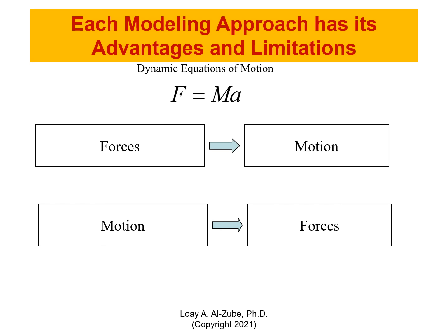The second step is formulating the equations of motion. And we have 2 ways. That's called the dynamic modeling approach. So we have something called forward dynamics and something called inverse dynamics. In forward dynamics, I'm giving you the forces and I'm asking you to find the motion. In inverse dynamics, I'm giving the motion and I'm trying to get the forces that created these motions.